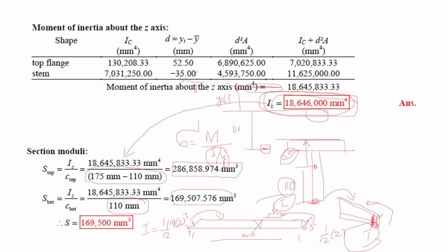So generally, why can you not bend the steel rule in vertical configuration? Because the value of I is more. The other one is less. That's why it's easy to bend. That's why you pick the controlling section modulus with a lower value, right? So students, here you don't need to use the vertical side, the horizontal side like this. Let me just erase this part.